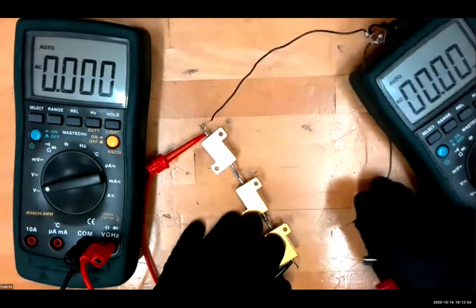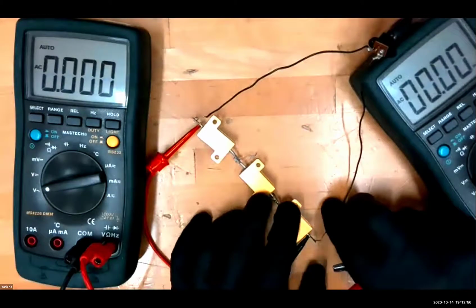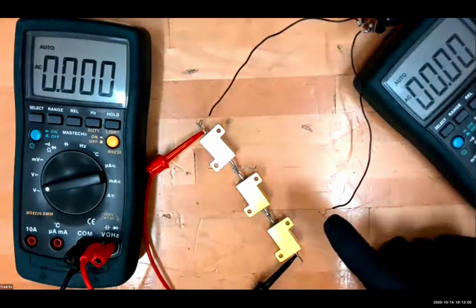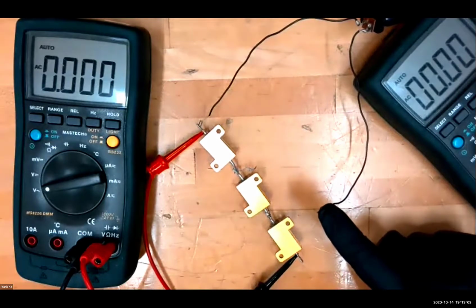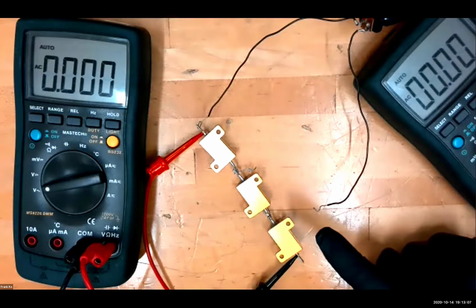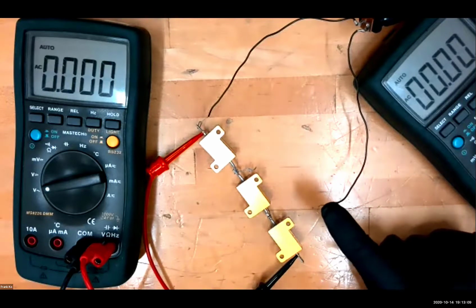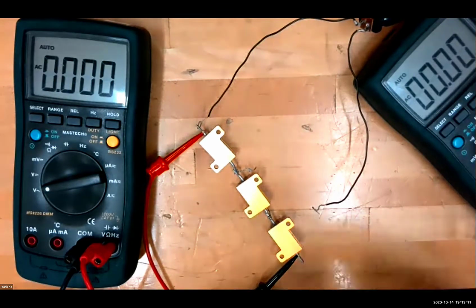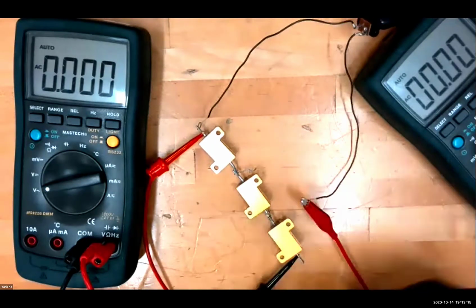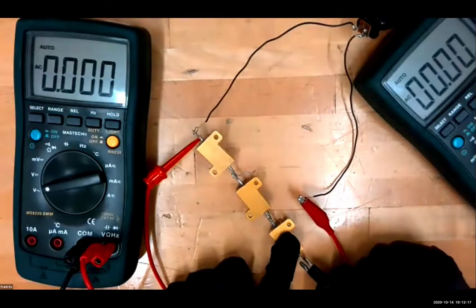I'm going to introduce the ammeter between where this wire normally would have hooked up for voltage. I break the circuit open. Have I created an open between this wire and this resistor? Are we looking at this? I have an open between this wire and this resistor. So I will hook up one lead here for the ammeter and the other one here for the ammeter.